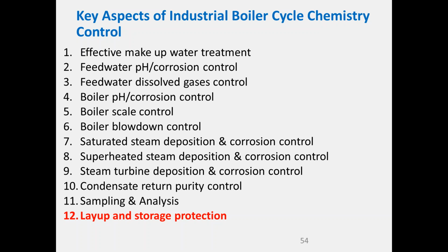If you've got a deaerator, having a dissolved oxygen analyzer on the outlet of that is quite useful, and often a pH meter on your feedwater. So again, if you're dosing ammonia or you're trying to get that pH of 9.8 to 10 in your feedwater, being able to verify that with a pH meter is very helpful. And then it also means that you can set up automatic control loops where you have a pump controlling to a set point, which lowers your manual operator intervention. And that would probably be my minimum recommendation there.